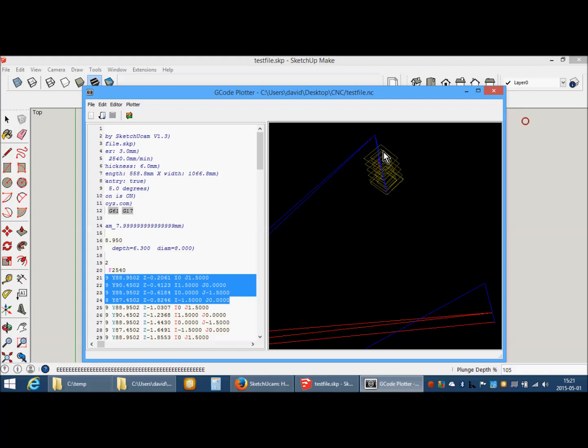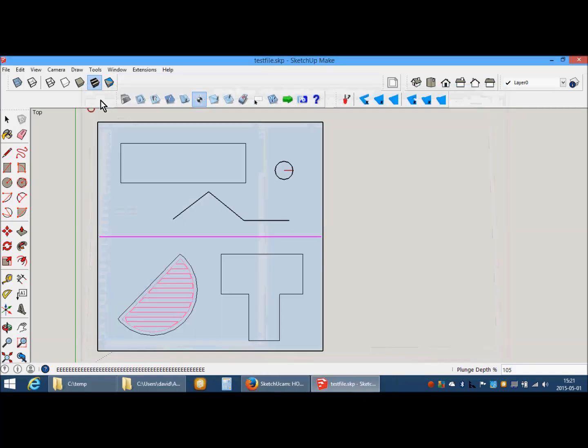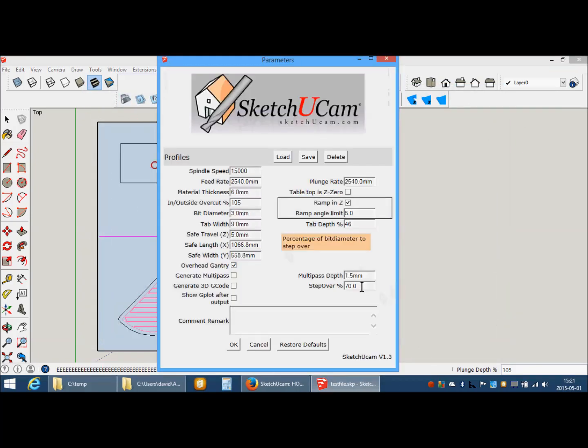size. Naturally, it is still using the step over percent, and if you have fuzzy hole boring turned on, it makes sure that all the passes are the same size, either using larger than step over percent if it's above 50%, or less than step over percent if it is less than 50%. 50% has been chosen as the breakpoint to determine an assumption of hard material or soft material.